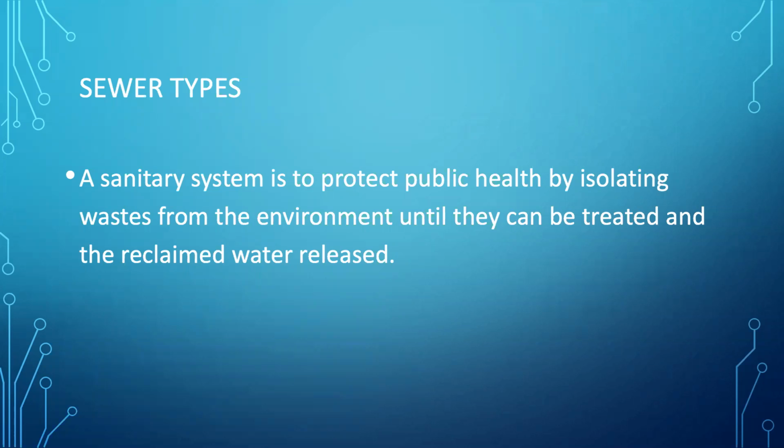So that brings up an interesting word. So the water in sanitary sewage, you'll see this word reclaimed water, and that's what they mean. They mean the treated water from the sanitary sewage, and then the residuals is what's left over, and that has to be dealt with in other ways, landfilling, coating it in chocolate and then selling it on the street, whatever's effective and legal. So when you see the word reclaimed water, it most often means water that was sanitary sewage that's been treated and now it's been reclaimed for higher beneficial use.